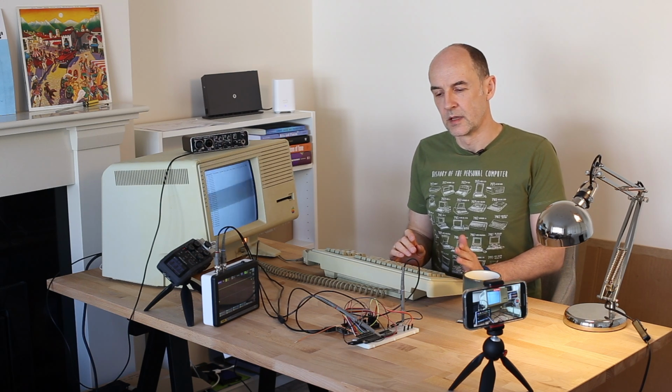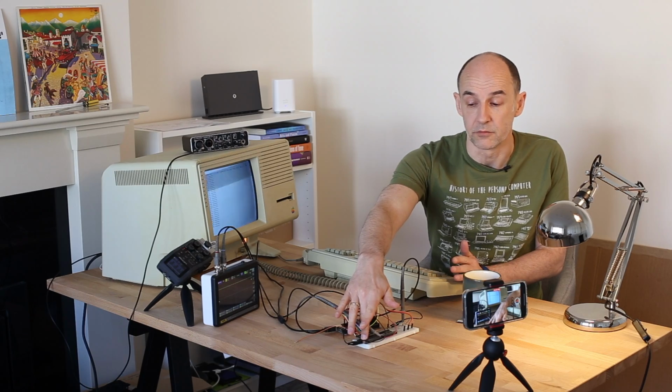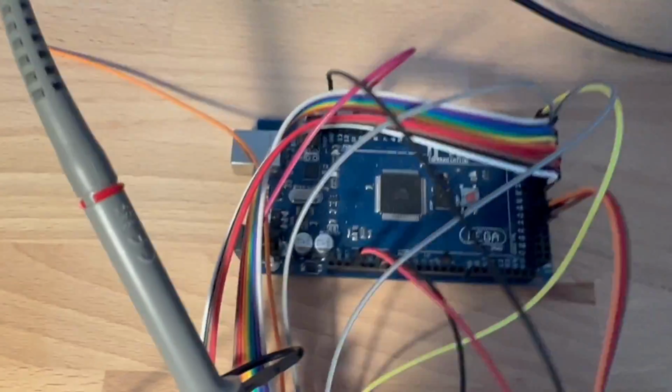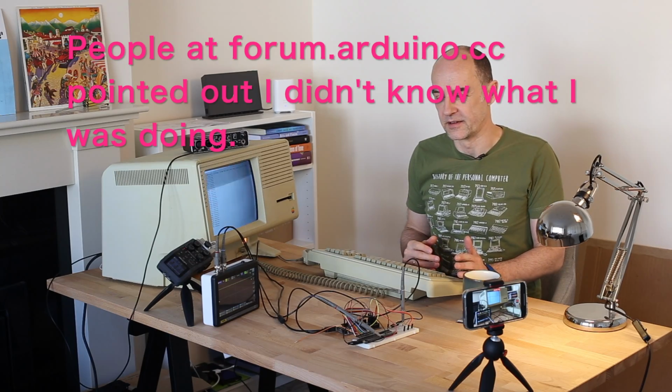That was the theory of shift register. I wanted to try it in practice. I wanted to reproduce the same way that Lisa controls its 6522, which then controls the sound wave. I wanted to reproduce that using an Arduino and an actual, original MOS 6522 chip. I connected it all together and I succeeded in making it run.